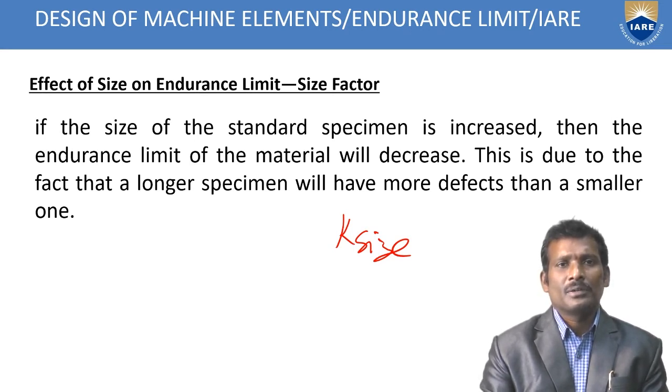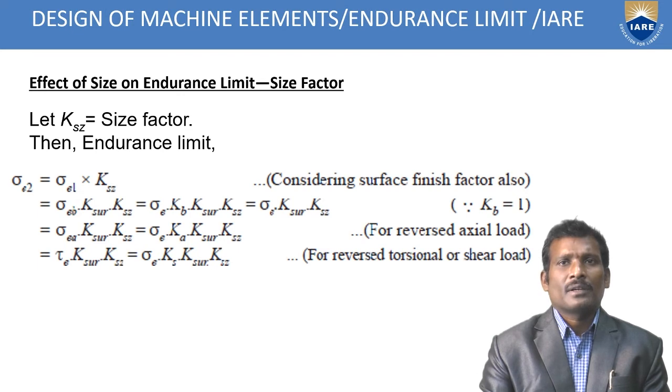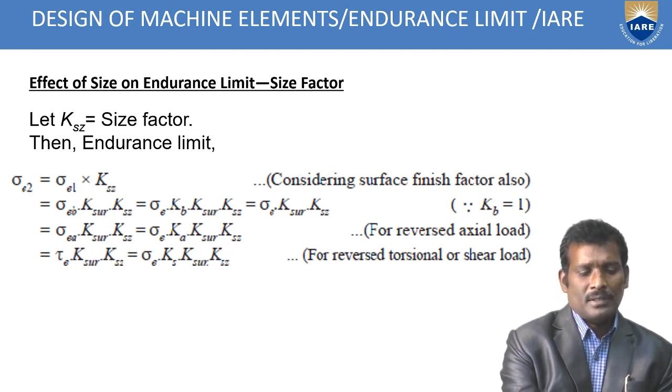We already discussed this in stress concentration. So the specimen will have more defects, and at that time you need to take some size factors. This is the effect of size on endurance limit, the size factor K size.